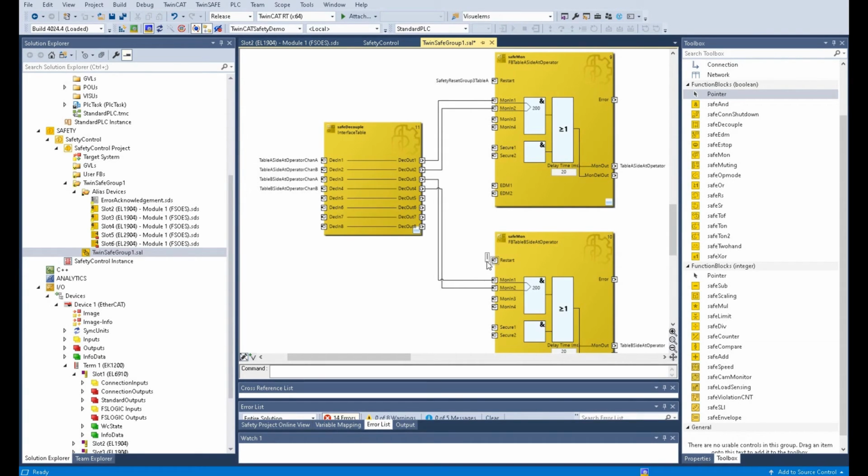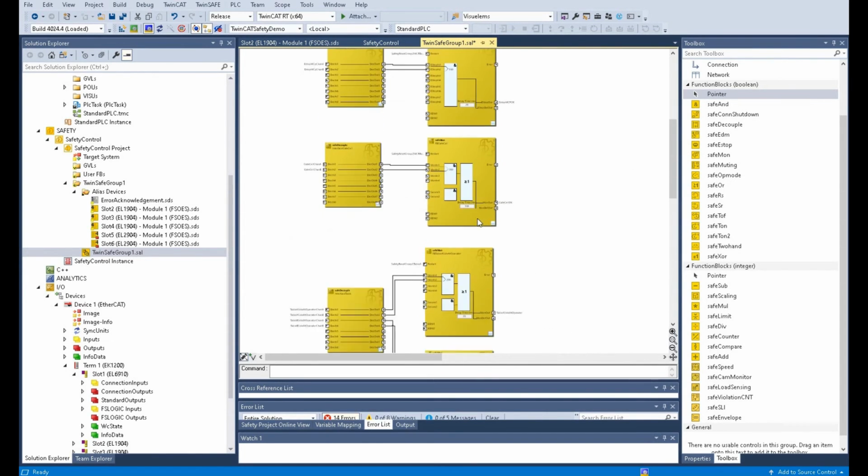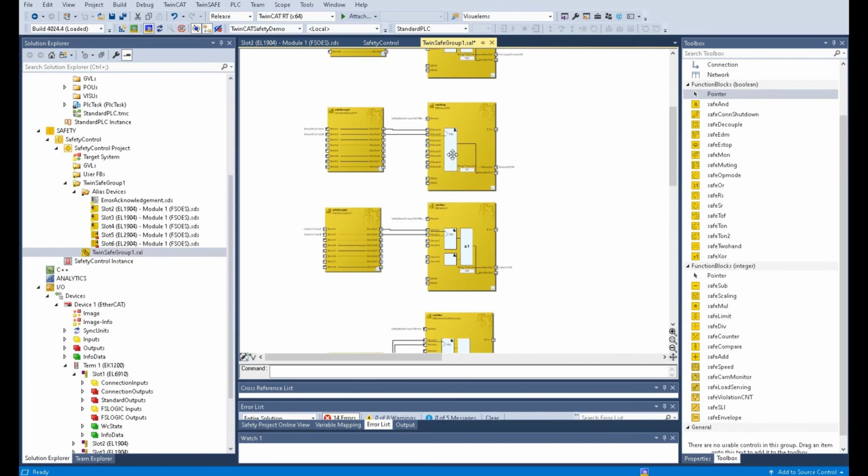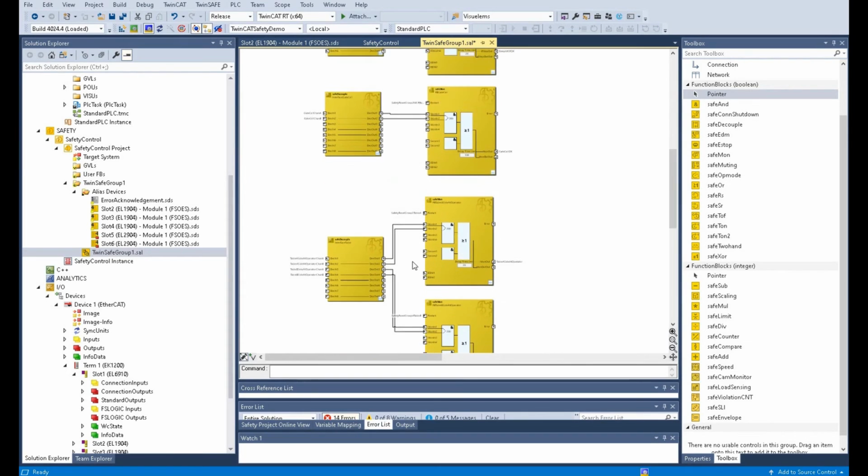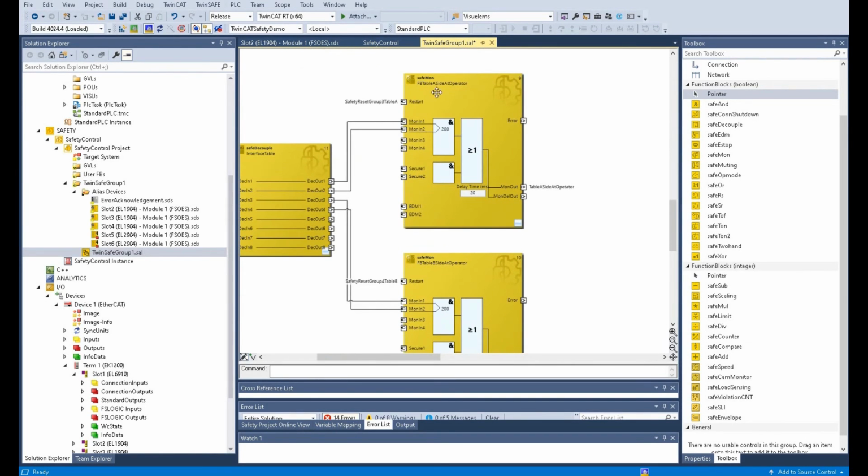And for the table B side, I will use another reset. Safety reset group 4, table B. We create the reset group, 4 groups here. One group for the light curtain, one group for the global cell MCP button to reset, and another 2 groups for the turntable.